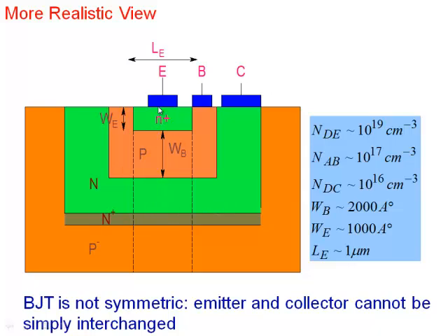Because note, the vertical dimensions that you see here are in thousands of angstrom, while the lateral dimensions are in microns. Could be 1 micron, could be 10 micron. Okay, so it's not drawn to scale. The lateral dimensions are, as I've shown here, the emitter length itself could be 1 micron. So laterally is pretty large, vertically is thin. And that's why N plus region has been added.